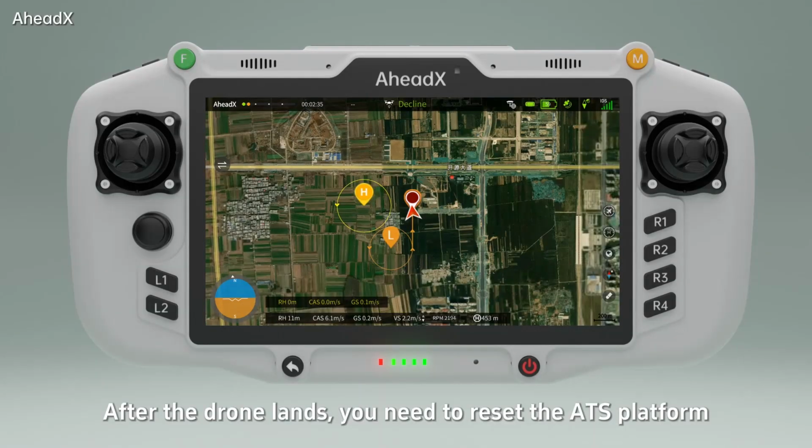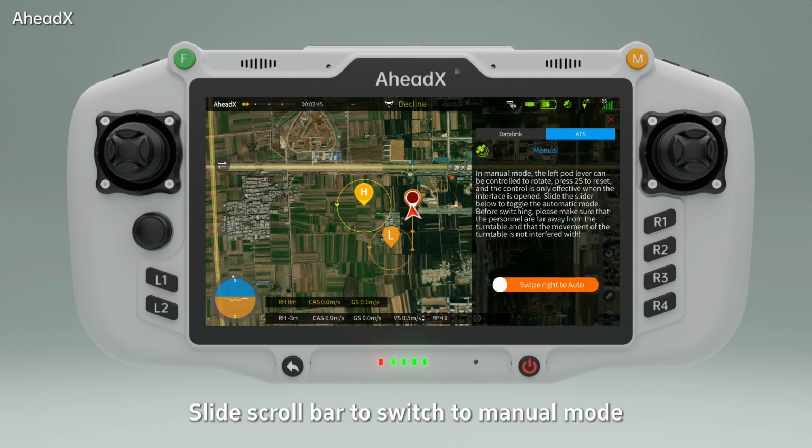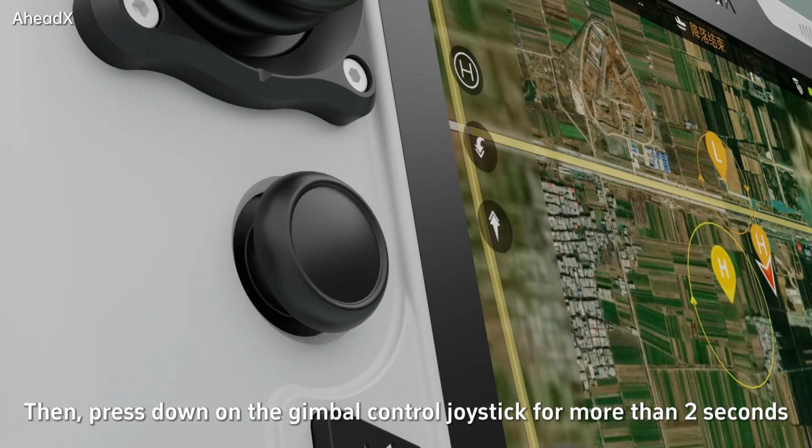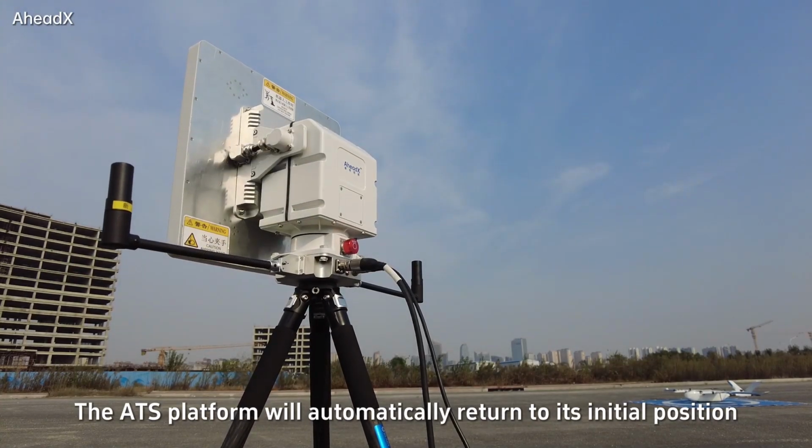After the drone lands, you need to reset the ATS platform or it won't fit correctly into the aviation box. On the ATS page, slide the scroll bar to switch to manual mode. Then, press down on the gimbal control joystick for more than 2 seconds. The ATS platform will automatically return to its initial position.